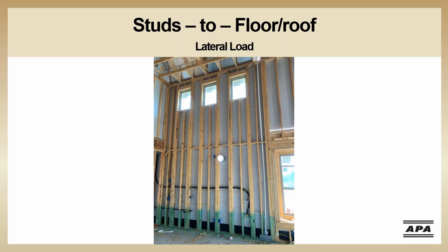One of the lateral load path failures we often see in this situation is when the studs do not span from floor to roof. Instead of a single long stud, we see two walls built of shorter studs and then stacked on top of each other. A single long stud designed to resist the wind load applied to it will be rigid enough to transfer that wind load to the floor and roof. But two walls stacked on top of each other will have a hinged joint that will not have the rigidity needed to transfer the wind load to the floor or roof.